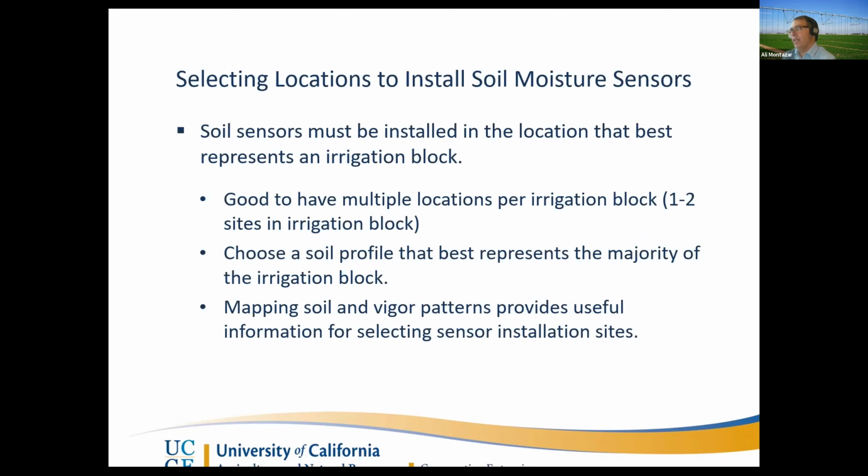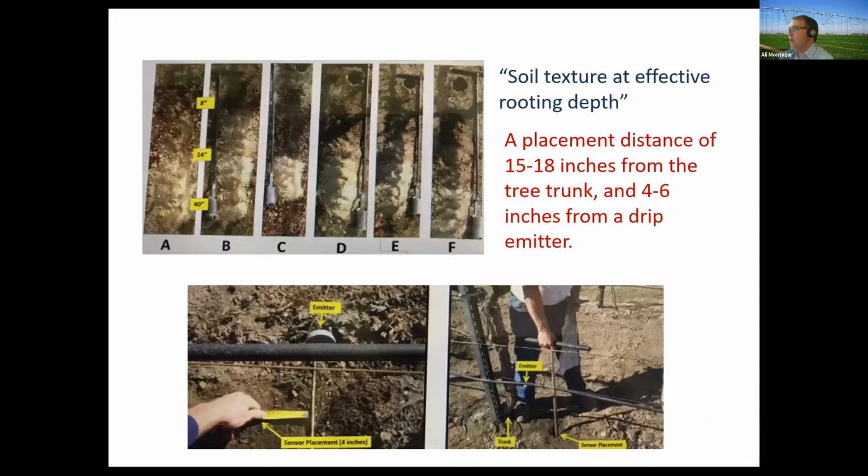They are very important. It doesn't matter which sensor you use, because all the soil moisture sensors on the market can answer all those questions I mentioned. So where we install them is very important. The location where we install them should represent the soil texture of the field.